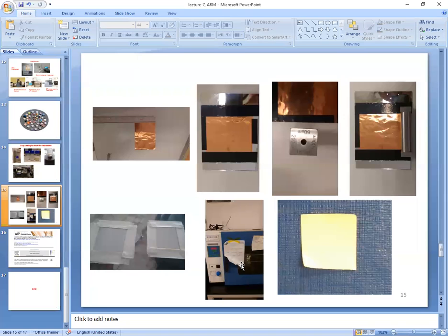So there is no calcination or sintering process in all this thick film process, because the materials are already made. You just have to mix the BNT powder, the crystalline powder, the already final product, into the PVDF or PVC polymer matrix, and then you just pour cast it on this substrate and heat it up.